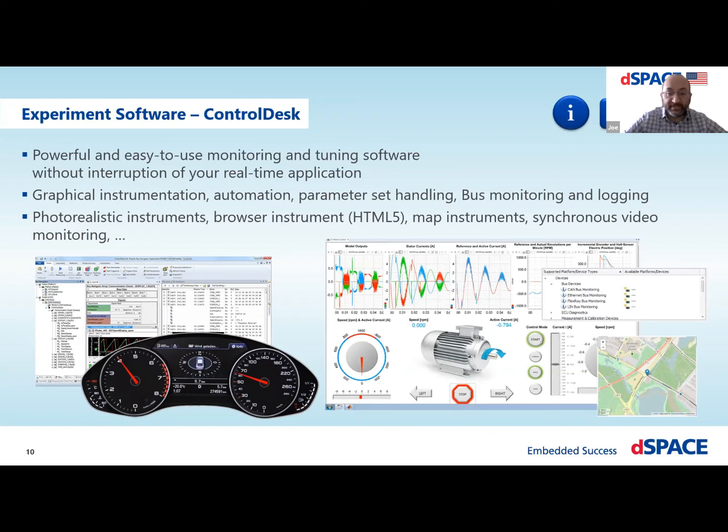ControlDesk offers a large range of instruments to use for that. So we have plotter arrays, XY plots. You can load even visuals, like graphics, to better illustrate what you're doing. There's all sorts of, obviously, numeric inputs and slider bars, rotary switches, anything that you might want. In addition to that, you can also basically do CAN logging and other types of logging directly in the tool itself. So this is sort of like your main user interface.